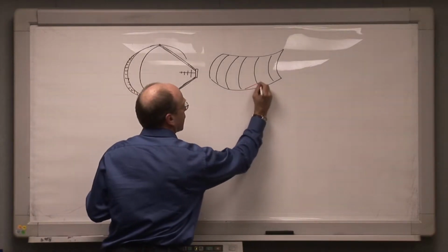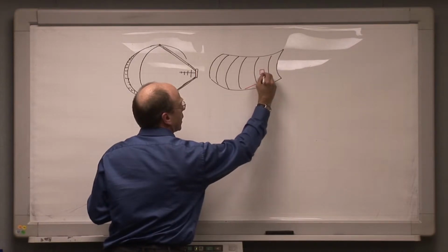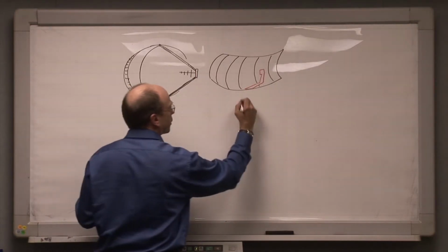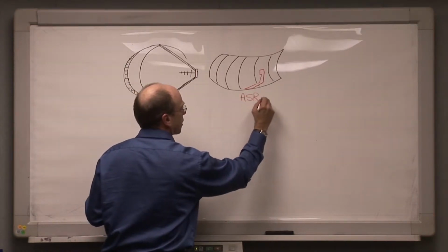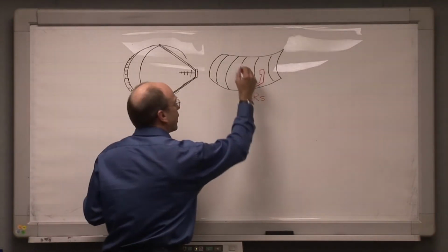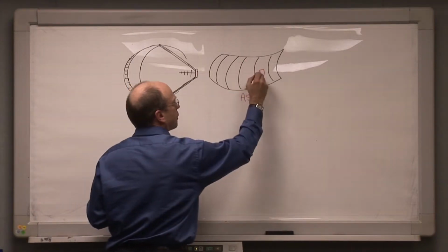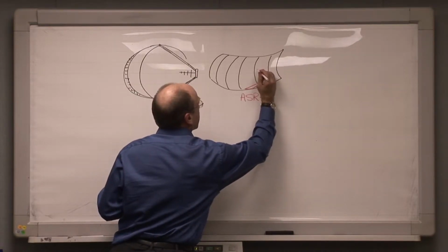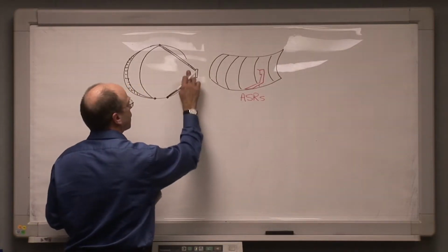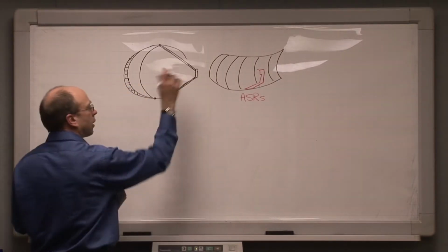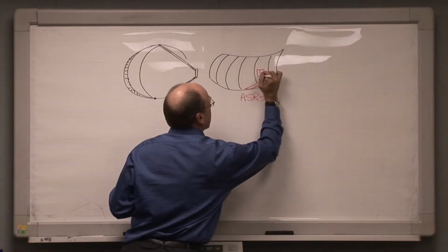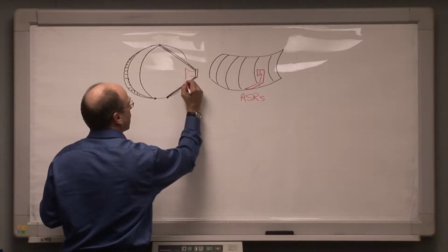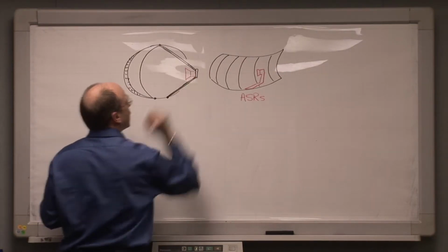Here the feed gets mounted out in front of the antenna reflector like so. And you see these on the FAA air traffic control radars. We've seen these, for example, on the ASRs in the earlier slideshows in this series. But the concept is the same. The energy is focused down to this point where an antenna is located. However, typically on these antennas, and also sometimes on the parabolic dish antennas, we don't necessarily use a log periodic. We could use instead a horn configuration, and this segues nicely into the next thing I'll mention.